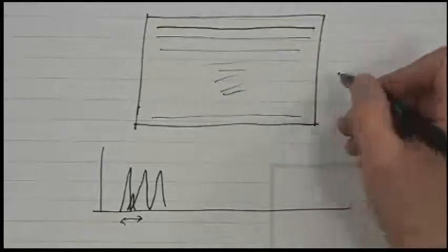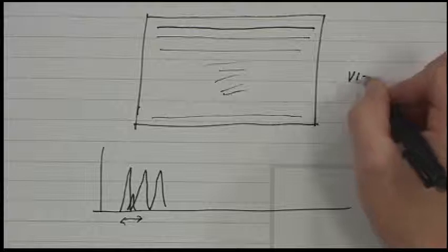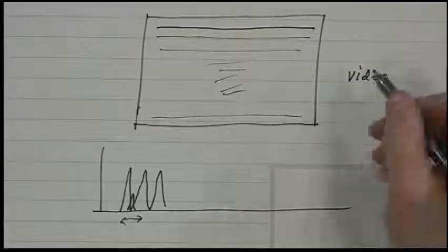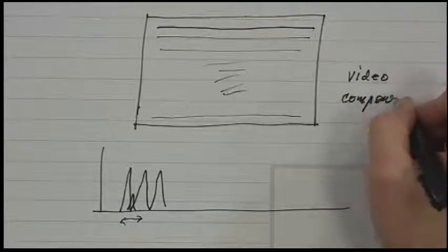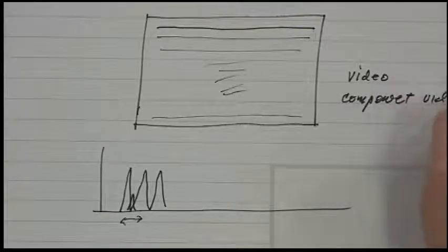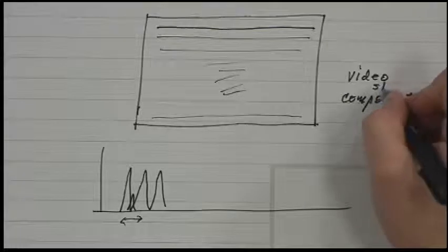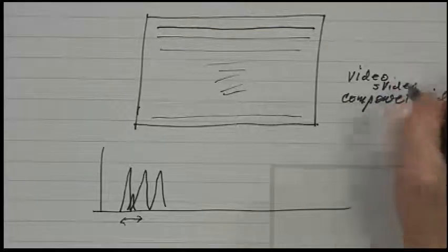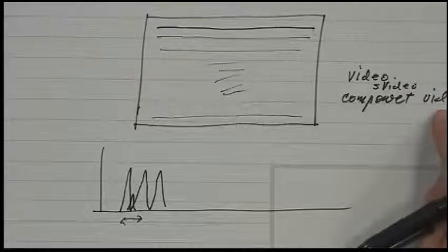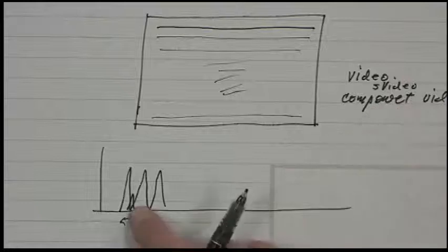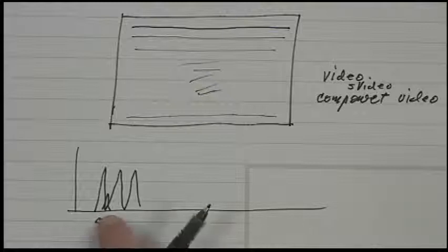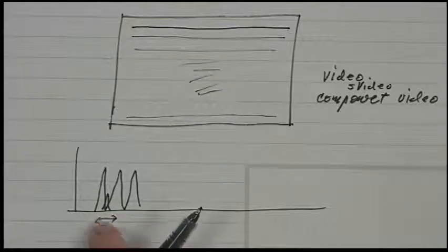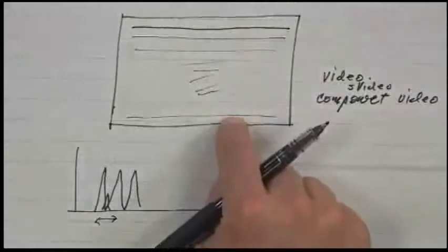So later, then, initially they just had video, and that was used for a long time. Okay, and then later there was component video. Actually, at one point there was also a thing called S-video. So S-video and component video were different mechanisms for just separating out the color channels. So later on, rather than actually adding these two signals together, they actually kept them separate so that you wouldn't have this crosstalk, and that would allow you to have higher frequencies in the vertical direction.